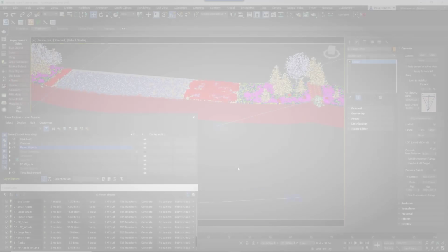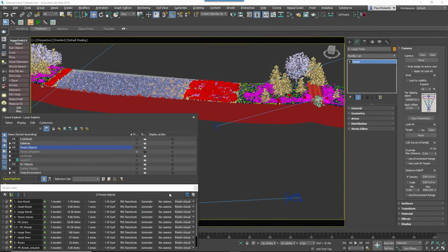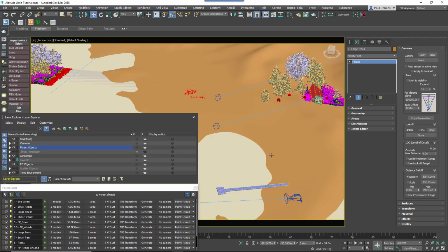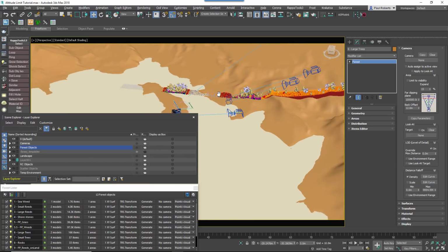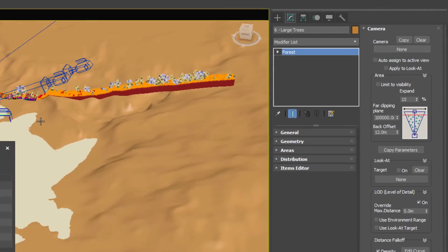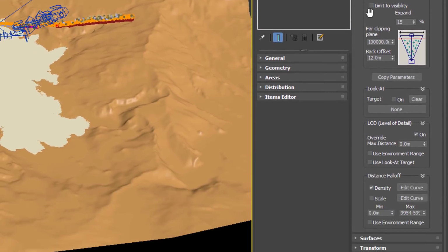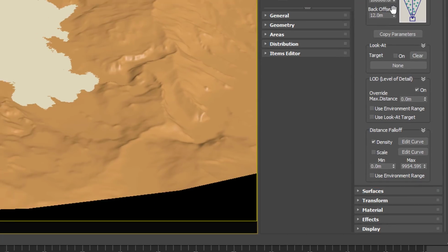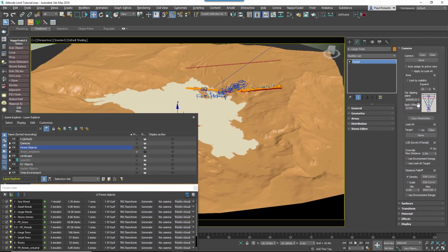Let's assume at this point that we have all the layers set up on the test terrain and that it's time to add them to the real scene. First, it's important to do some optimization. Several of these objects have had very high density, and applying them to a terrain several kilometers wide is, well, not a sensible idea. There are two easy optimizations that should be applied to nearly any object: camera culling and distance-based fall-off and clipping. Camera culling can be applied to more or less everything.